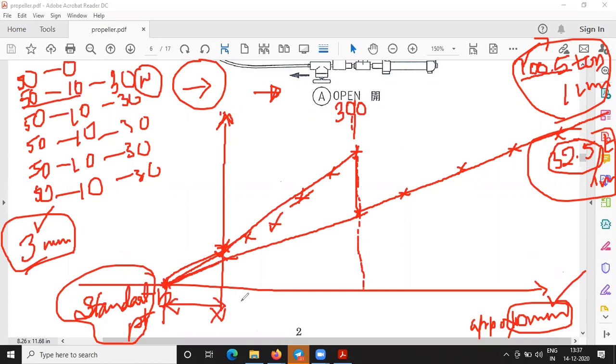You understand? Sir, repeat again, sir. Okay. Initially, I have told you, without the rise, what happens? You are given a 50 bar pressure. If there was a gap, then it would have moved 10 mm for you, like this. But for this 50 bar pressure, you adjusted the dial gauge to 0, taking that as an initial point. That means the 50 bar you have given initially is now gone waste. Yes or no?